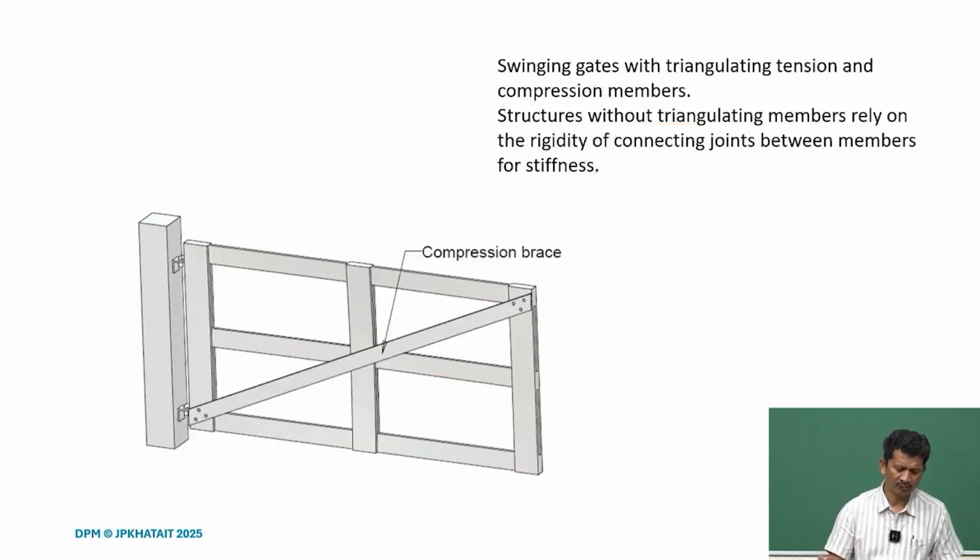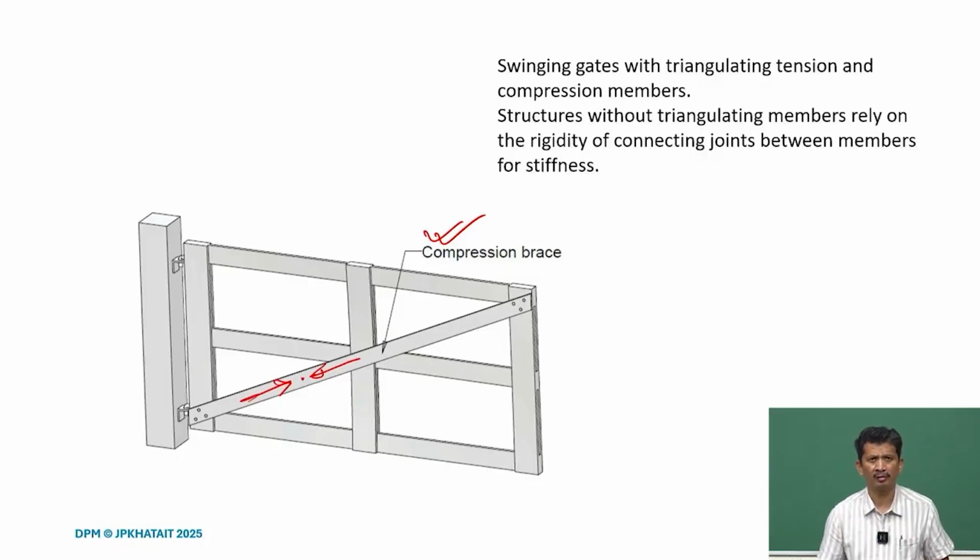At the same time, suppose we want to just use a compressive member, it's the other way around. Because of this length, if you take any cross section, there will be compressive load coming, so it will also be prone to sagging. So this will not be possible in this case. Triangulation is a very good solution, and depending on the nature of the force coming on the member, if it's just tensile, we can usually use any kind of flexible steel cables and resolve it. We can see this these days in many furniture designs.